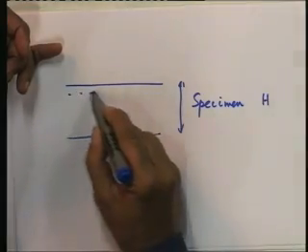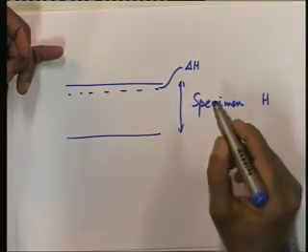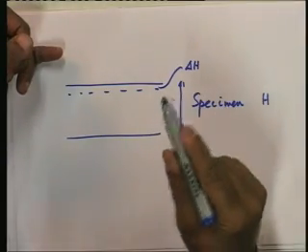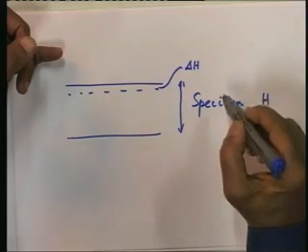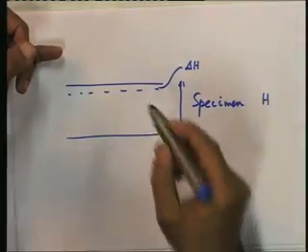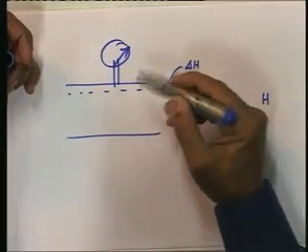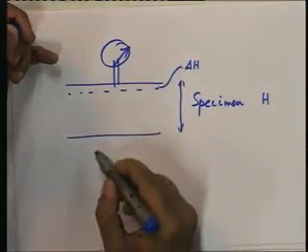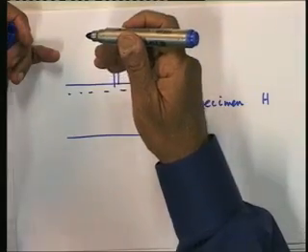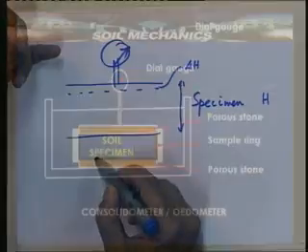The change in thickness, say delta h, that takes place with every application of load increment can in fact be measured. So, there is this dial gauge which keeps on measuring the change in thickness. So, we can take readings of this dial gauge, readings of this compression at different time values.